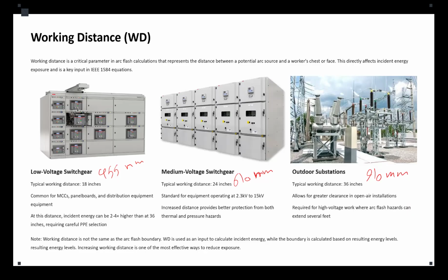Okay, if you underestimate the working distance, the calculated incident energy will be artificially high. Okay, and if you overestimate that, the result will be dangerously low. So you need to pay attention to that. Now, that's why IEEE 1584 actually recommends using the standardized working distance unless there is an actual measurement or safety policy that is dictated otherwise.